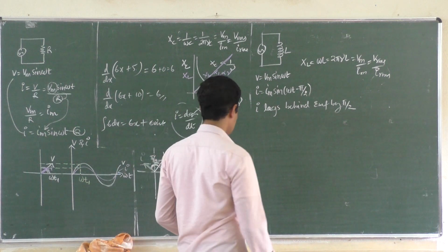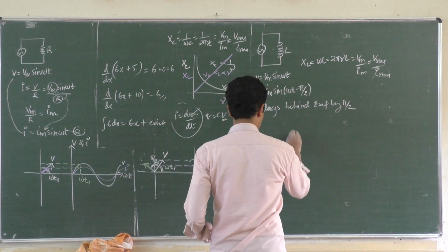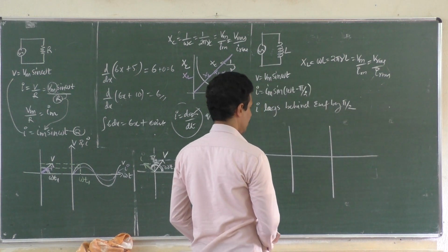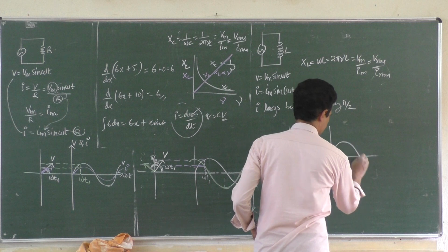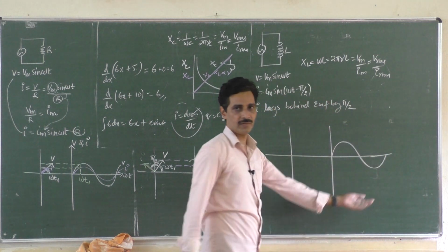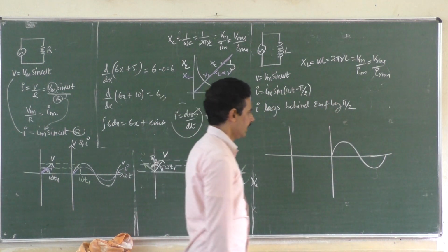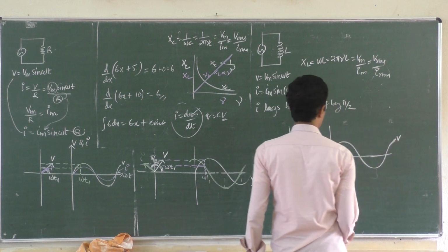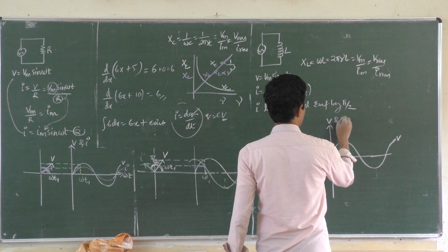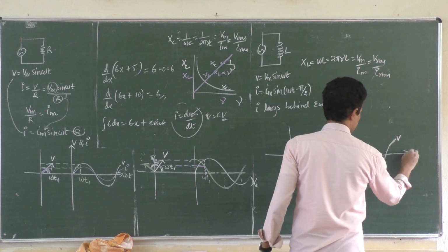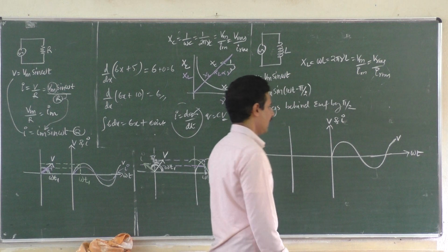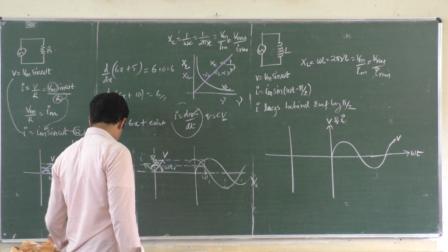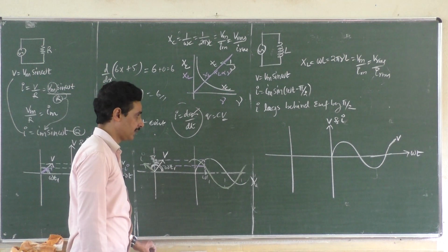Now if you want to draw the phasor diagram and wave diagram, yes, we will represent voltage first. Hope you can see this. Yes, now the full board is visible. This is voltage. Okay, I'll represent it here itself. This is V and I both. This is omega t. How will the current be? Current should lag behind, right? Current should lag behind the voltage.